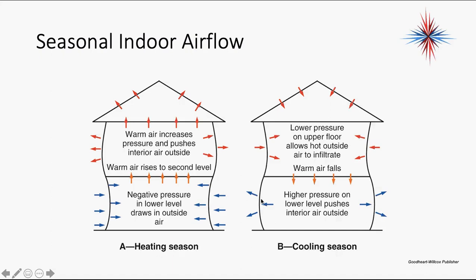These are very minute pressures, but the cool air tries to escape from the bottom of the house, and the warm air replaces it. You can tell this by holding your hand over electrical outlets on some of the walls, hopefully just the exterior walls, but sometimes you can actually feel this happen in the interior walls as well. That's called building leakage.